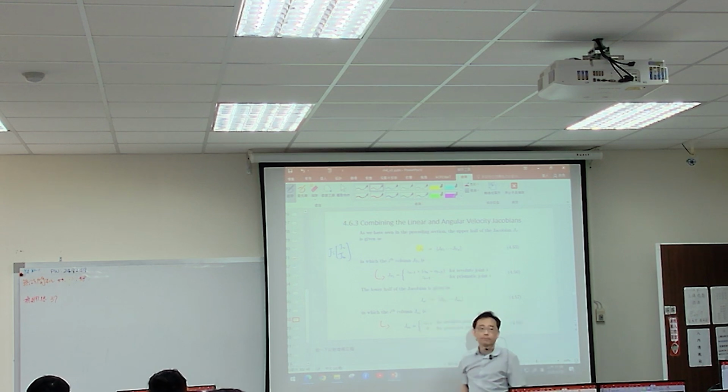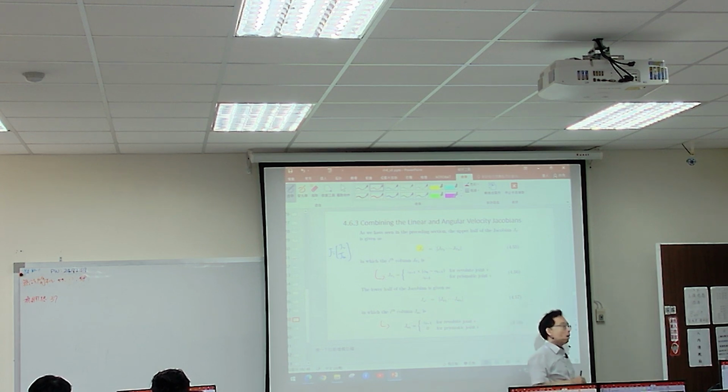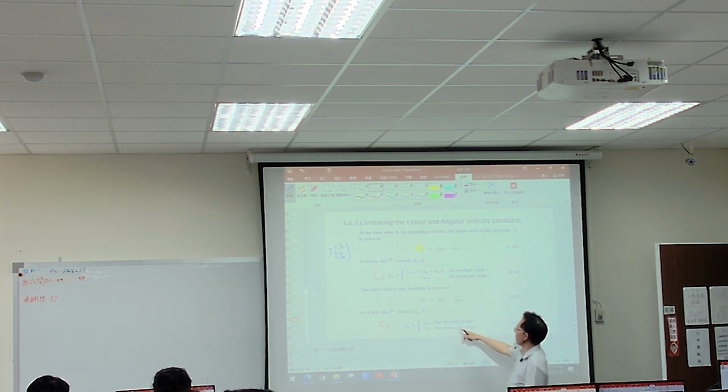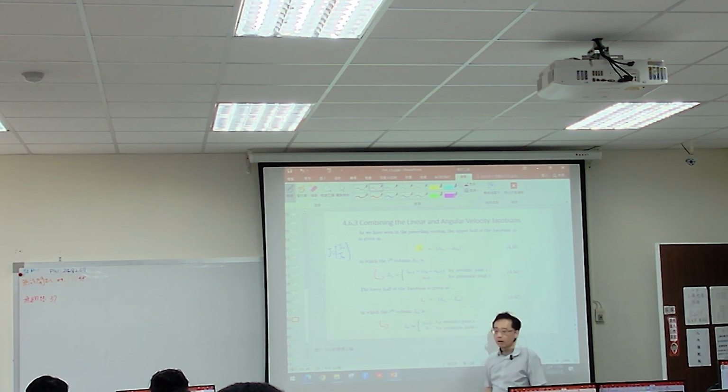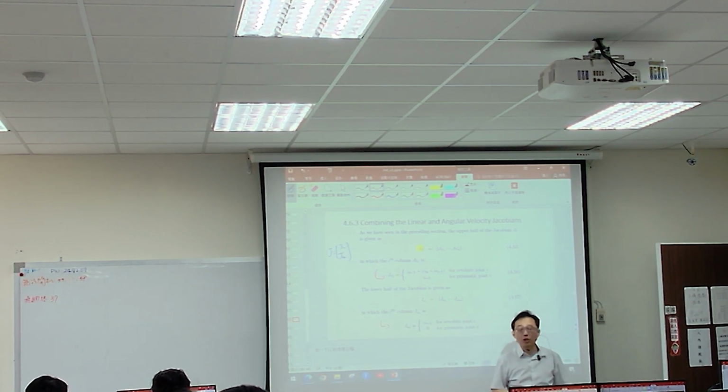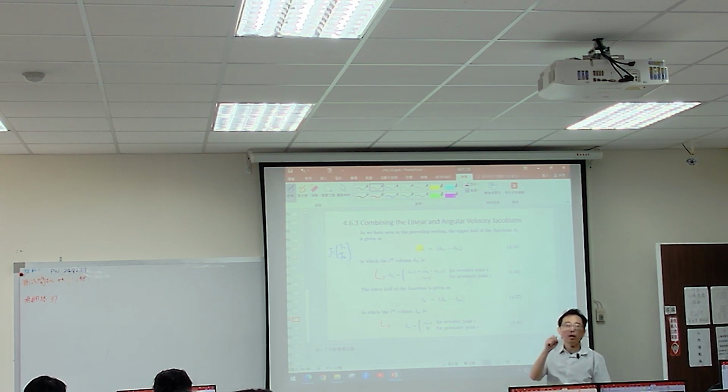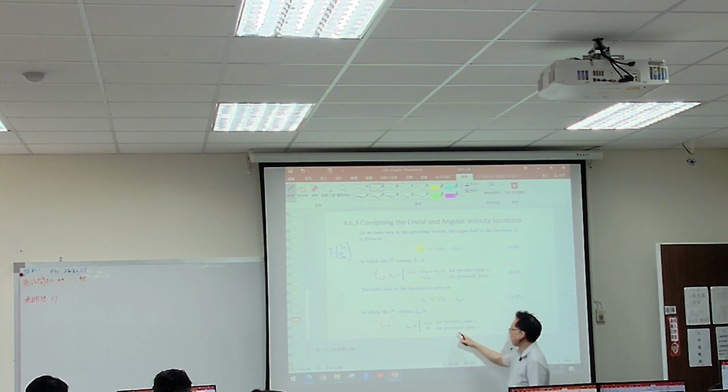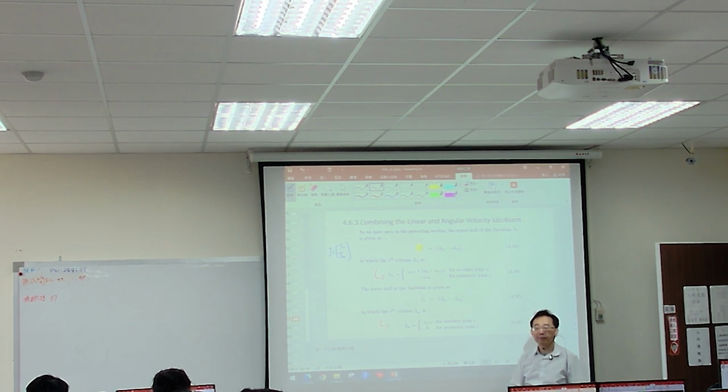For the J omega, it is rotation velocity, so rotation velocity is easier. For the revolute joint, we just put the rotation joint vector, which is the link origin. But for the prismatic, it is 0.